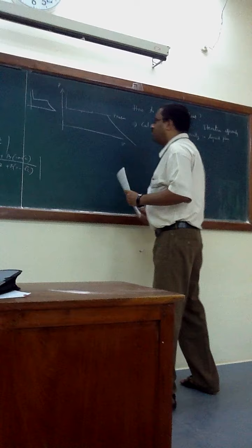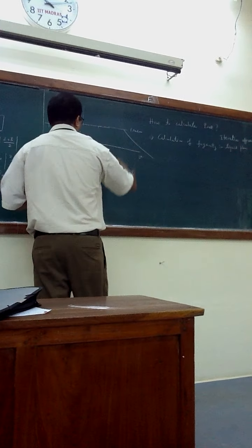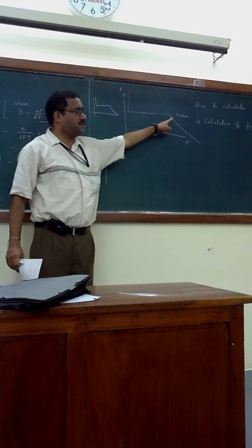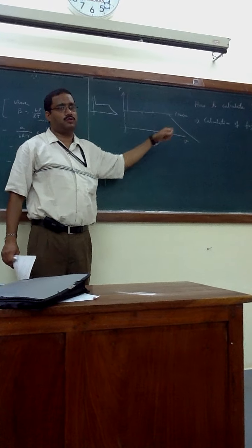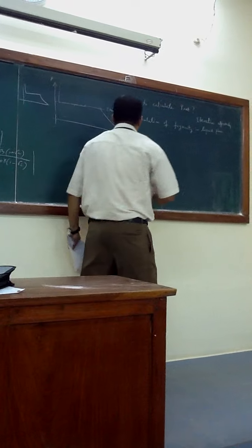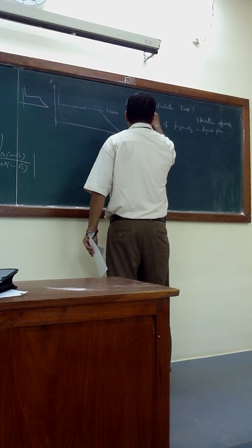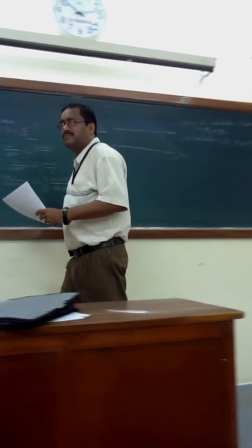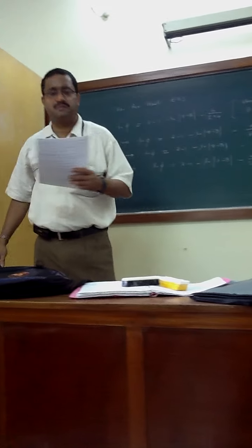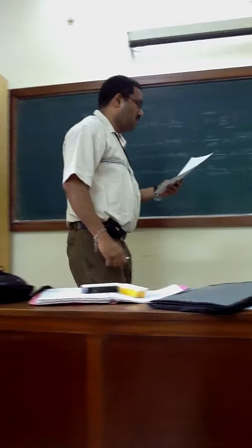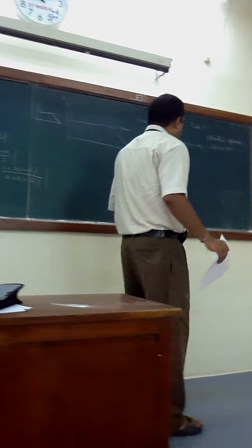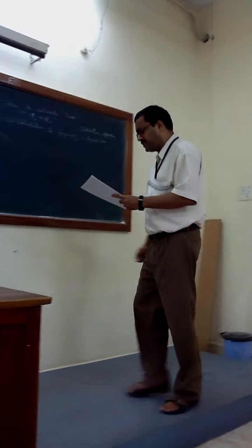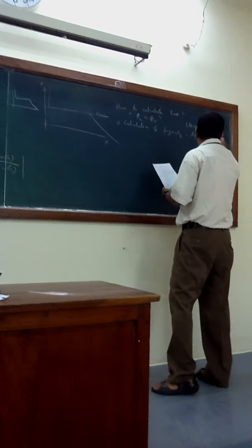So what we are going to do here, very simple, is vapor liquid equilibrium, right? This is your V L, this is your V G, and at these 2 points, phi L equals phi V. So our basic principle to calculate this P sat is phi L equals phi V. That's the basic principle. So when you talk about the liquid phase, the phase change will occur at the P sat and go to the vapor phase. Focus on the liquid phase and vapor phase.